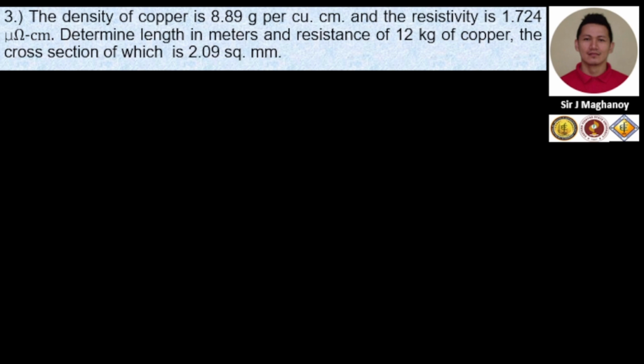Okay, so let's evaluate the problem. We are tasked to determine the length and the resistance. We all know that length and resistance are directly proportional. If we recall our formula, our resistance is equal to resistivity times length all over the cross-sectional area.